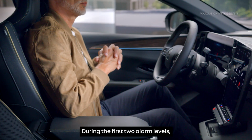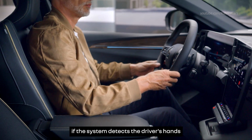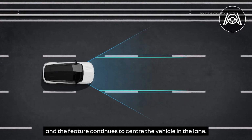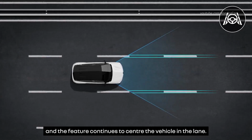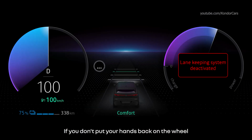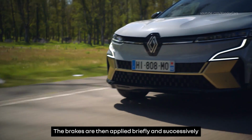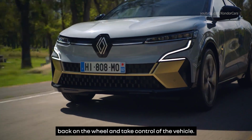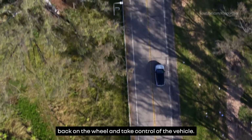During the first two alarm levels, if the system detects the driver's hands on the steering wheel again, the alarms stop and the feature continues to center the vehicle in the lane. If you don't put your hands back on the wheel within 45 seconds, the indicator light flashes on the instrument panel and an audible warning will sound. The brakes are then applied briefly and successively to warn you that you need to put your hands back on the wheel and take control of the vehicle.